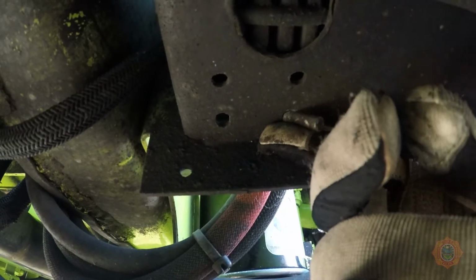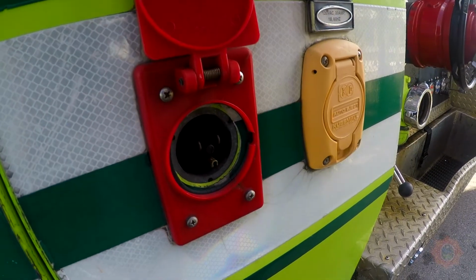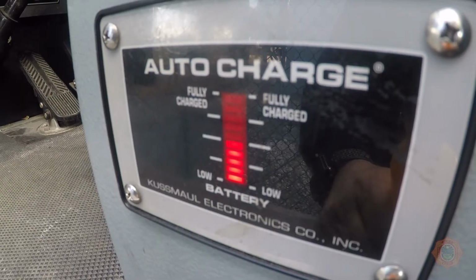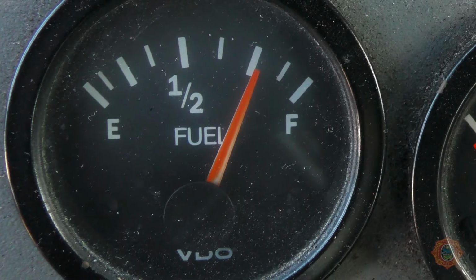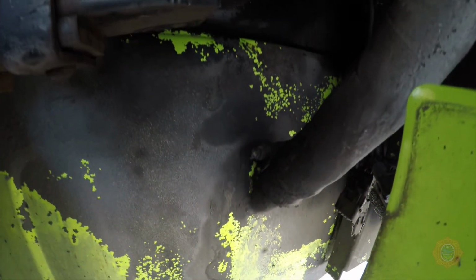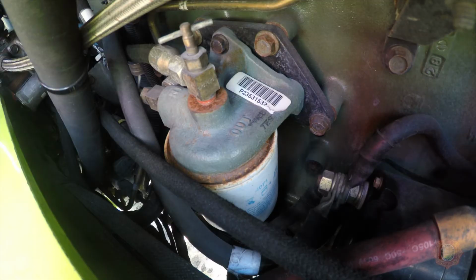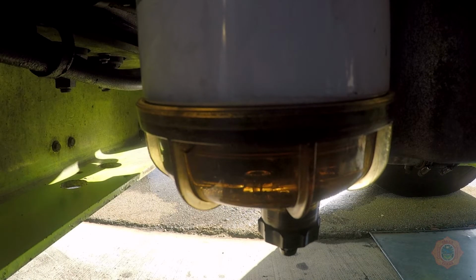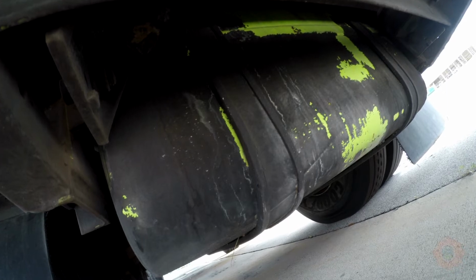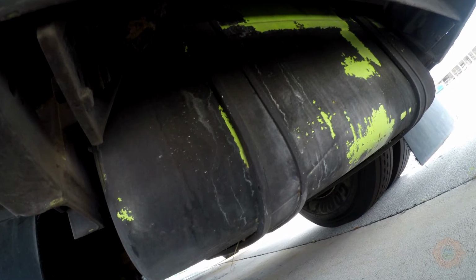Check the battery tie downs, ensuring that the battery is held firmly in place. Check the built-in battery charger, ensuring proper operation. Inspect the fuel system. Maintain the apparatus within the minimum fuel tank level per policy. Check for any leaks. Check the fuel system filters for any indication of contamination, water, or debris via the filter sight bowls. Inspect the fuel mounting straps for security and corrosion.